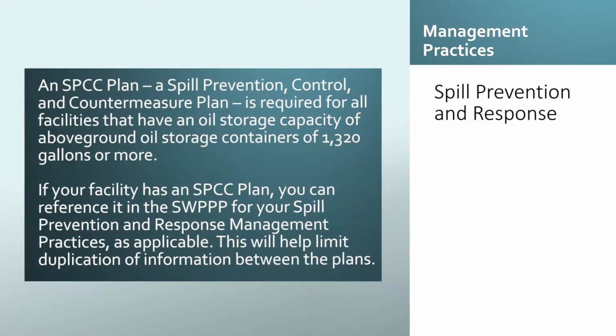An SPCC plan, a spill prevention, control, and countermeasure plan, is required for all facilities that have an above-ground oil storage capacity of 1,320 gallons or more. If your facility has an SPCC plan, you can reference it in the SWPPP for your spill prevention and response management practices as applicable. This will help limit duplication of information between the plans.